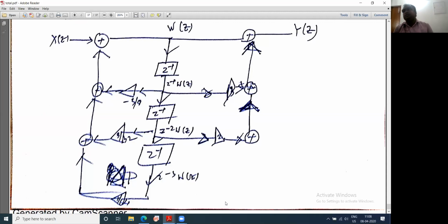I have said delay is essentially realized in digital systems using a D flip-flop. In a D flip-flop, you have some input present at the D terminal, and the output will be Q and Q bar. With every clock pulse, every bit appears at the output from the input. So every input will be delayed by a clock. So delay is essentially realized using a D flip-flop.